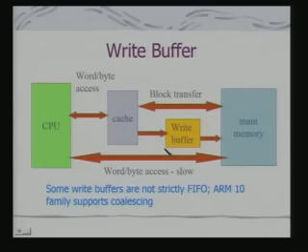These write buffers in many cases are implemented as FIFO memory. You have seen hardware stack memory, where you can push the PC in case of a subroutine call or an interrupt. This is an example where in many cases you have hardware FIFO memory. So, effectively a queue. Why is it a queue? Simply because I am storing the data sequentially.